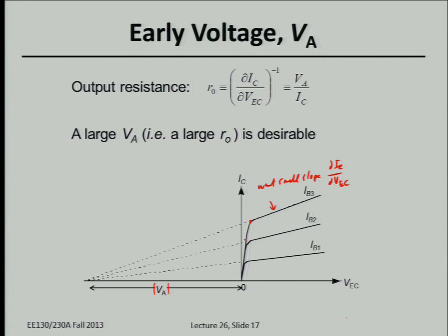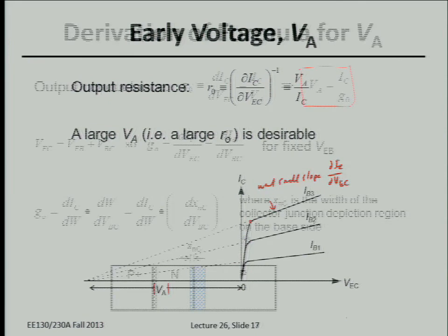So you're forward biasing the collector junction when you start to see this current fall down in the saturation regime. Usually that means the collector junction is counteracting the built-in emitter junction forward bias. So bottom line, the voltage VEC is rather small in the saturation regime. We're approximating that it's close to 0, and that's why this simple equation for the early voltage actually works pretty well.